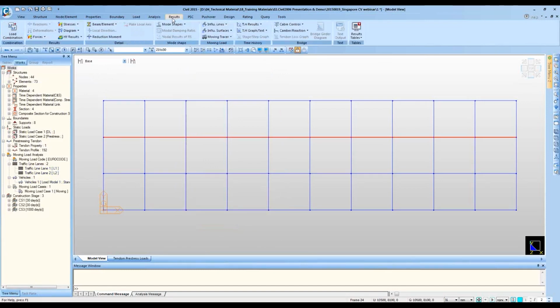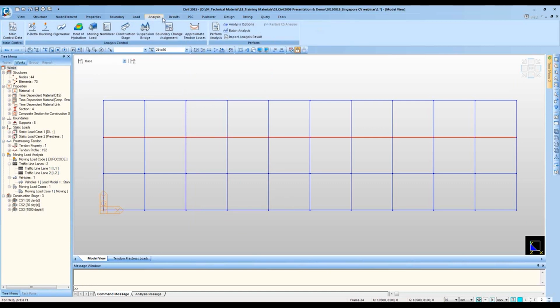When you are working with the moving load analysis, you know the results we are getting, like moment or shear force, they are not the concurrent force. They do not exist at the same time. Like the vehicle position when shear force becoming maximum and moment becoming maximum, all vehicle positions are not same.